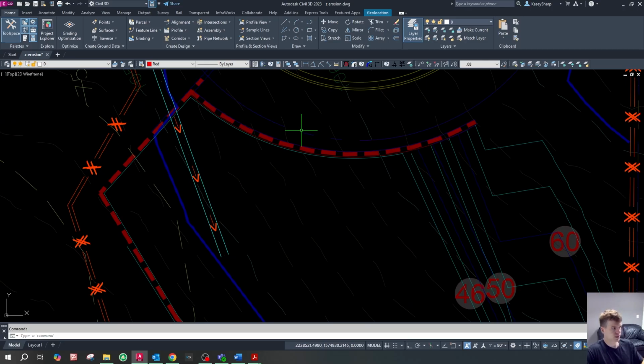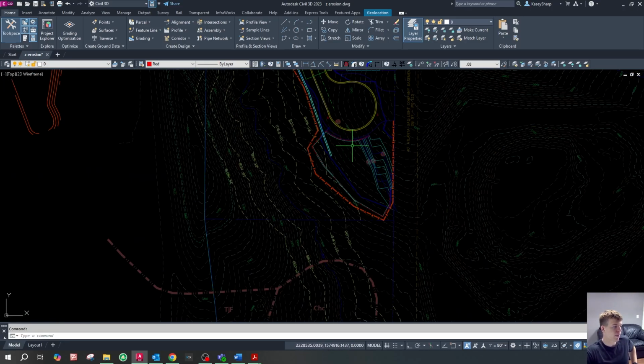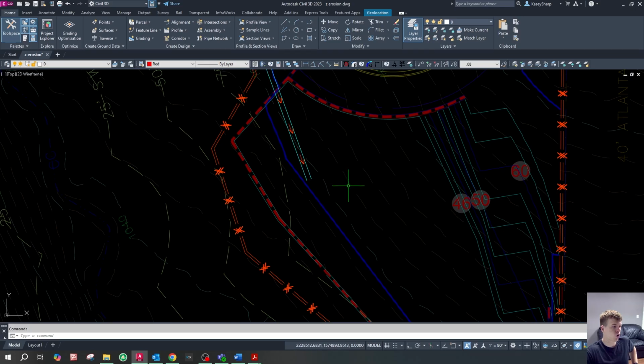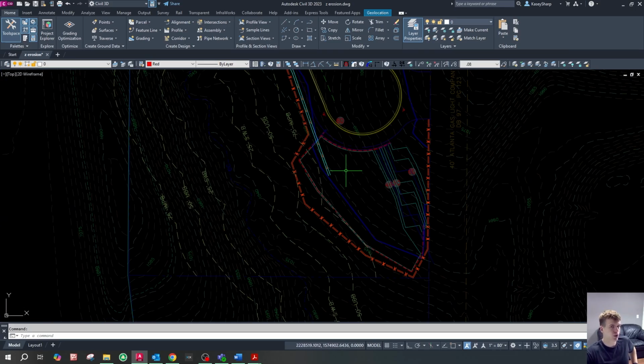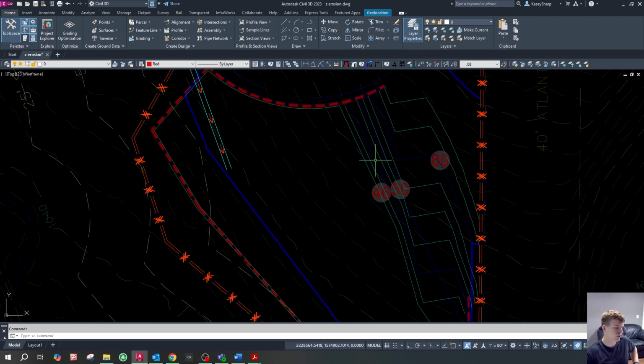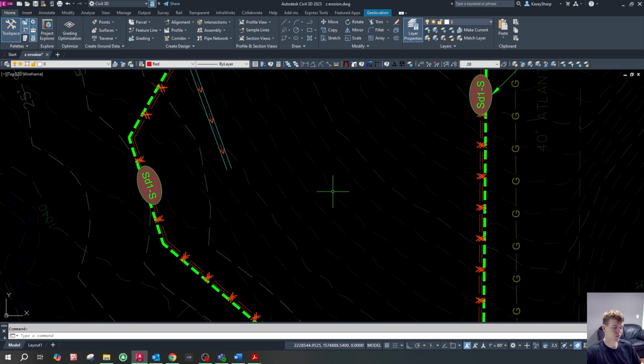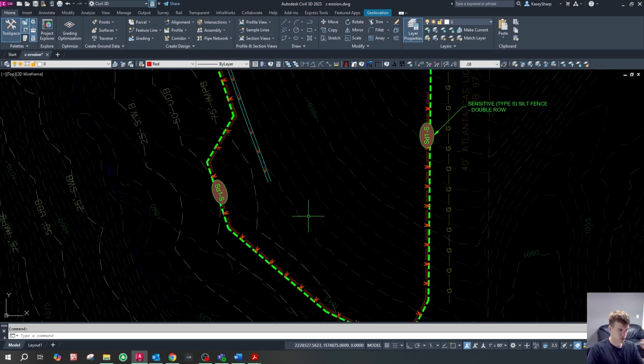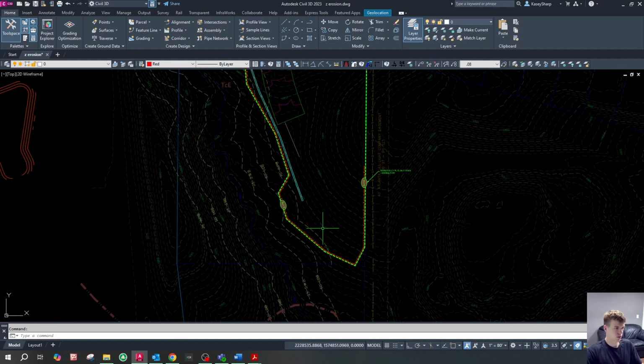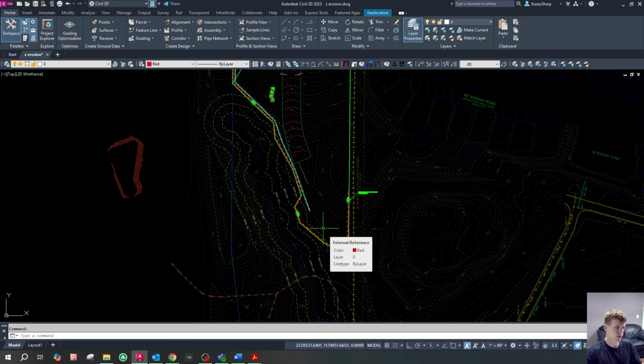like I was saying before, because this is a unique case where we have the retaining wall here, it makes it a little bit more tricky because we're just going to have to grade in like a hole in this spot. But if you have a traditional detention pond that just has 2-to-1 slopes and a pond berm, you can just copy those contours and paste them into your phase 1, and then maybe delete some of the bottom contours so it's not as deep, because it likely doesn't have to be as deep as the pond is. And then you can just leave those contours there, copied exactly like the detention pond is. So then the contractor is literally just getting a head start on grading their pond. It also just looks cleaner as you transition from phase 1 to phase 2 to phase 3.